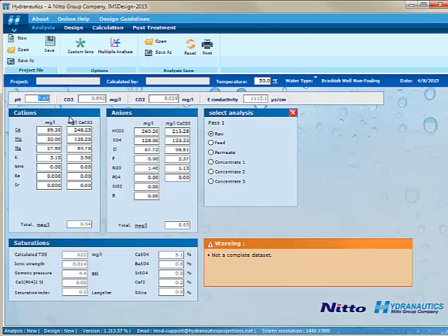And so I've entered all the values into the cations and anions. Notice they can convert it automatically from milligrams per liter to milligrams per liter as CaCO3. That's there. And then if you want to balance the data set, I would definitely focus on either chloride, sulfate, or something else that's in this anion list to get it balanced. You'll see a warning, you don't see the warning here, but you will see one. And you just click on the parameter and it will auto balance it.